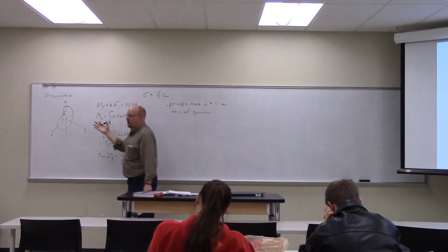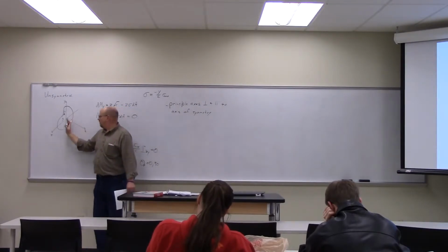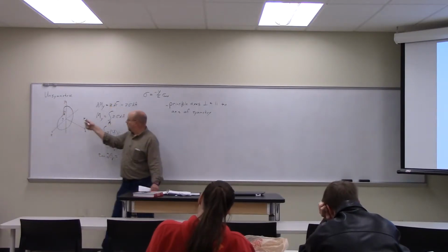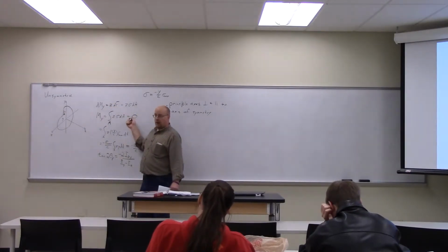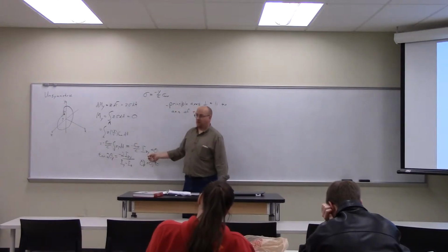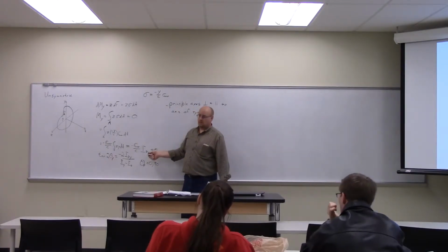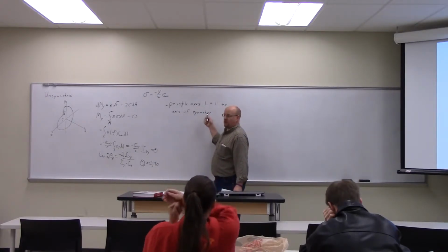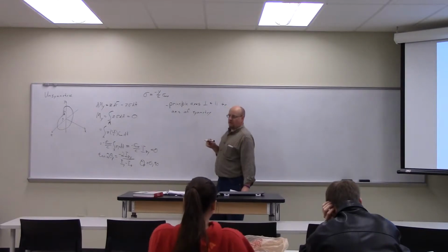Because if I have symmetry along y, then that means I have an equal moment on either side of y. Therefore, the sum of the moments equals 0 about y, therefore I'm at the principal axis. So if I've got principal axes, they're always going to be lined up perpendicular to or parallel with the line of symmetry.